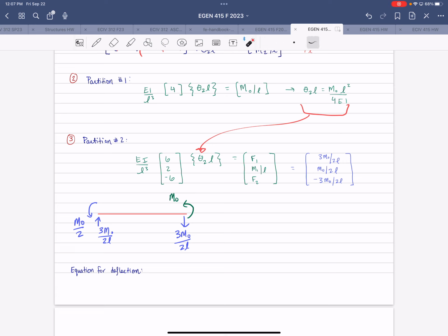So now that we have appropriately applied our results according to the finite element sign convention, we can step out of the finite element analysis and apply our regular mechanics sign convention, which we know means a negative moment at the left end for counterclockwise. So a positive result in finite element analysis, interpret that as counterclockwise. Step out of finite element analysis, negative moment if you were to draw shear moment diagrams and things like that.